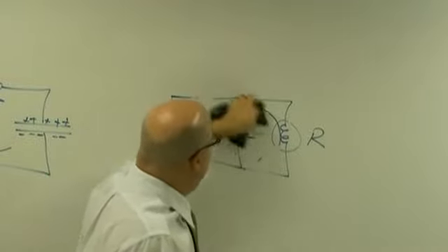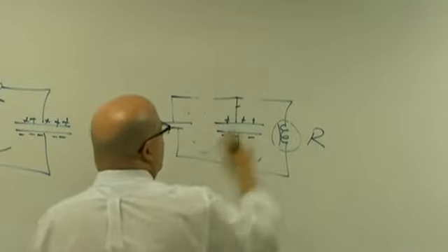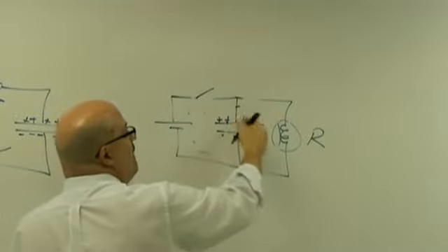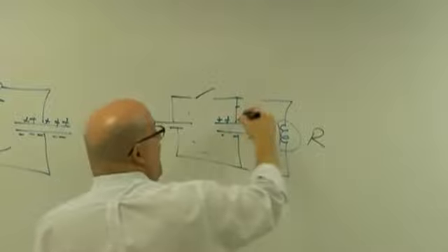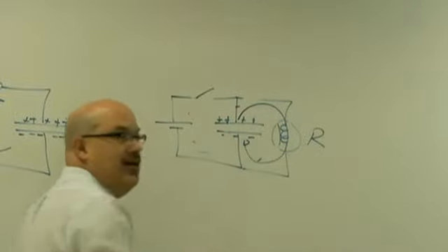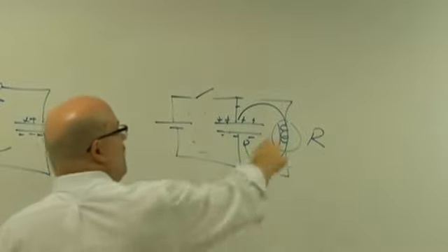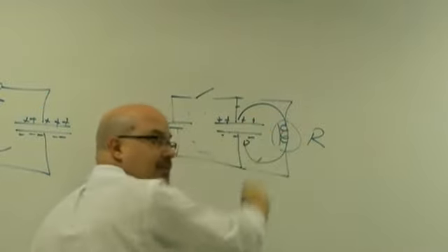Now look what happens when the switch opens up. The current goes from there to there. This switch is open, but now I have high volts here connected through this bulb, right? And so current's going to flow through here. Through the bulb it continues to go the same direction, but it goes the opposite direction through here now.